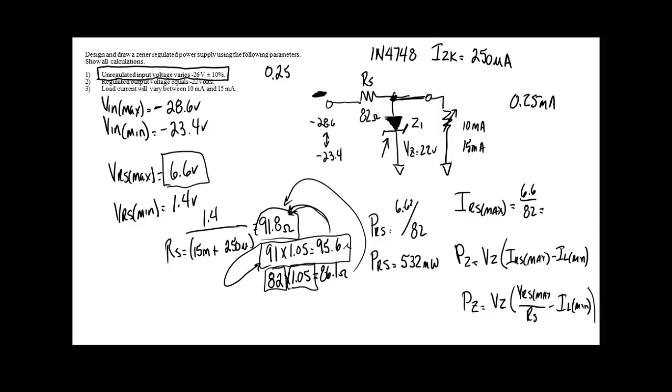So 30 volt power supply, I'm going to take 30 and square it and divide it by 100 ohms. So that's 9 watts. So that's putting a quarter watt resistor on a circuit that was developing 9 watts worth of power. And what did it do? It just burned it up. And what were they doing? They were blaming it on their power supply.